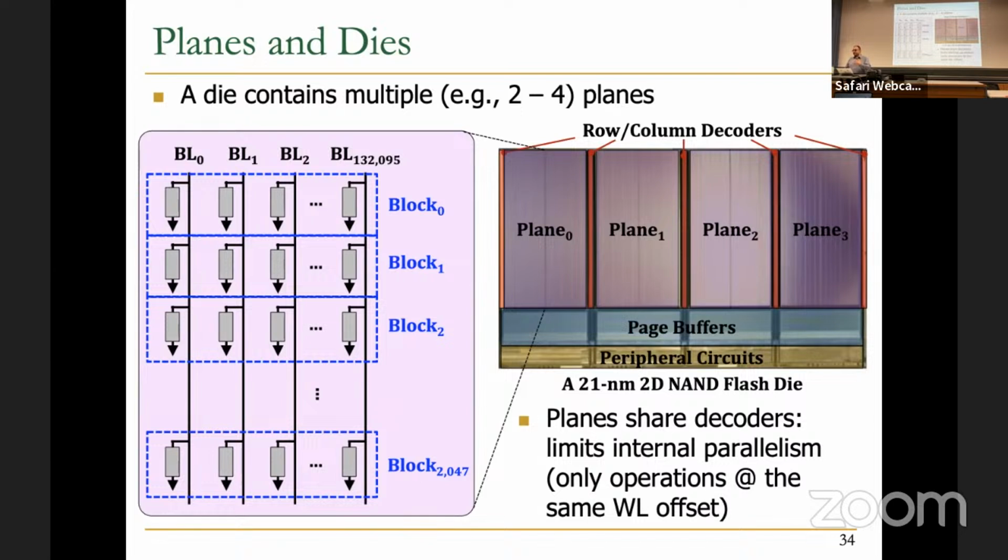So the question is how likely we can get multi-plane operations. If you want to make it more likely, you need to control it. When you do a write operation and at garbage collection, you need to dictate multi-plane operations. That's what we're going to see, and that's one of the reasons that brings us to the trade-off. Sometimes dictating multi-plane operations can cause some other overheads, and you need to do it intelligently, which is not easy to do.